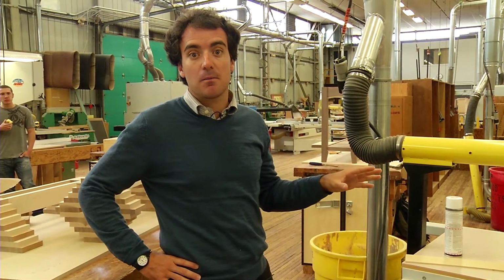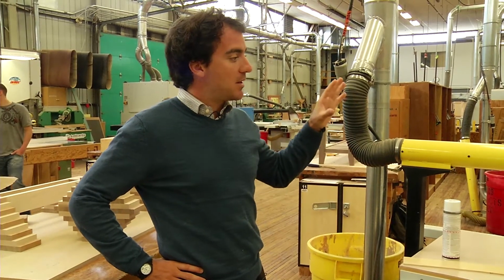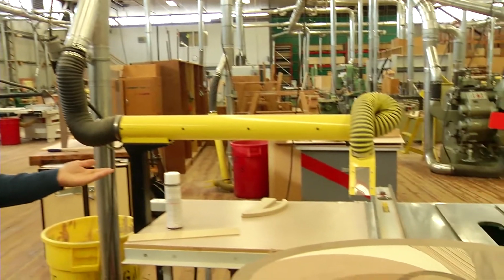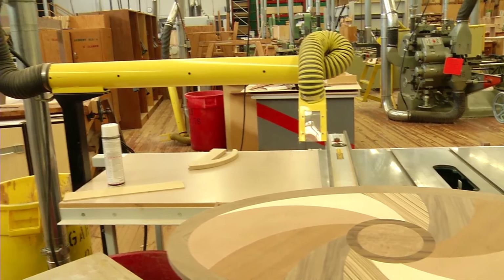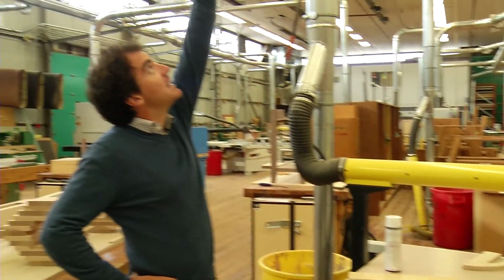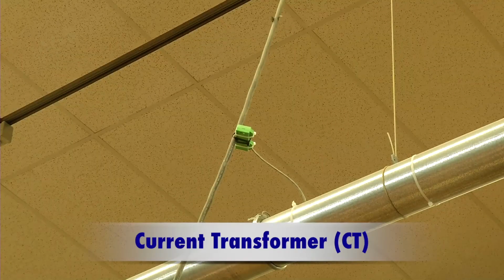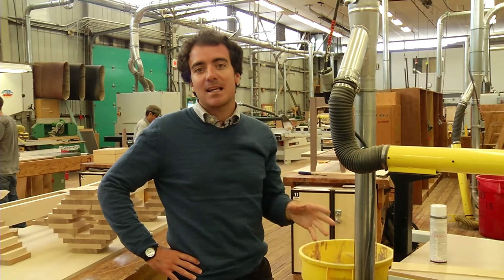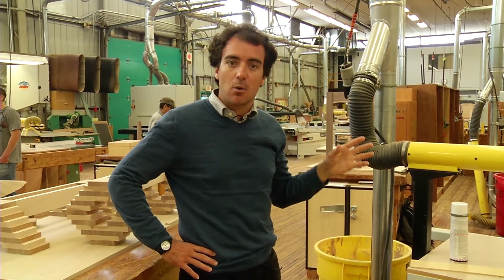With the old system, which was a constant volume on or off system, there would be dust extraction happening right now at this workstation even though no one is using it, even though no dust has been generated. With the new approach, what we have is a CT that is attached to the main feed to the workstation. The CT is the little green box that you see up there. The CT is actually sensing if there's a current, in other words, sensing if someone is using the workstation.